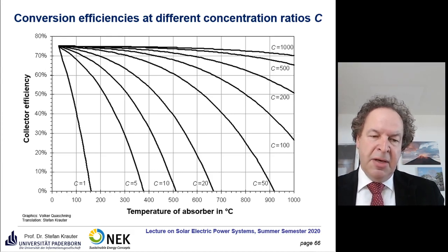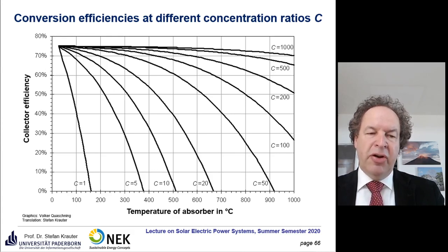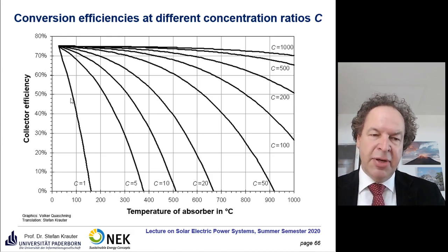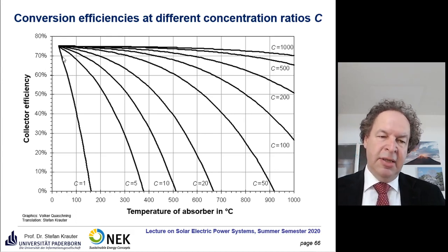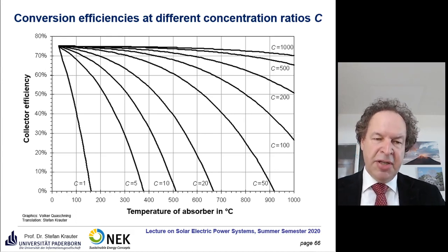And sure, at this efficiency, if you have a collector and you want to achieve the maximum temperature, you shouldn't push any water through it, and therefore the collector efficiency is 0. If you let a lot of water flow through it, then efficiency goes up, but then the achievable temperature is much lower. So if you follow this line going up, then efficiency is higher because you profit from all the thermal energy there, but the achievable temperature is very low.